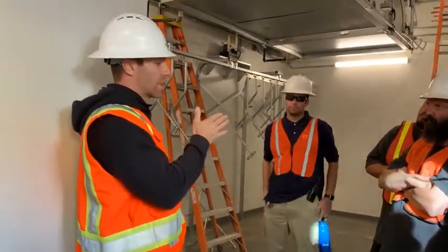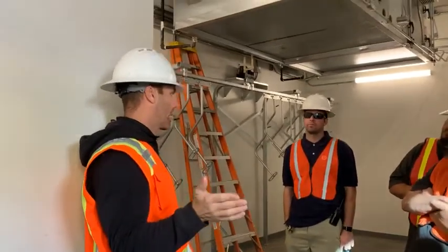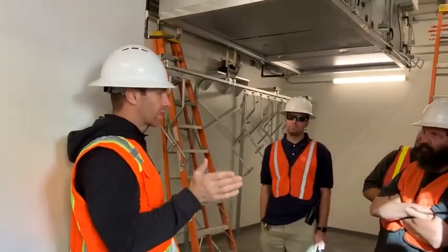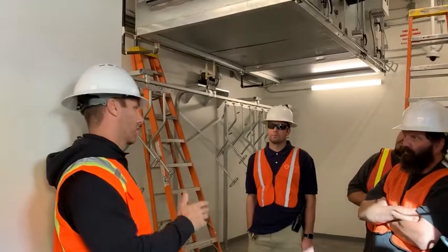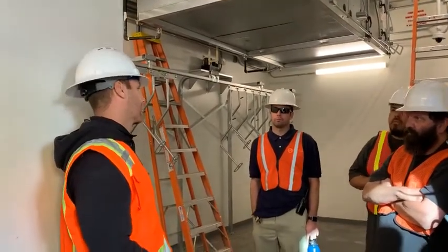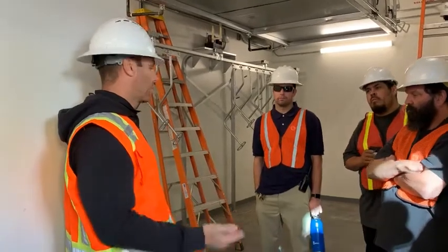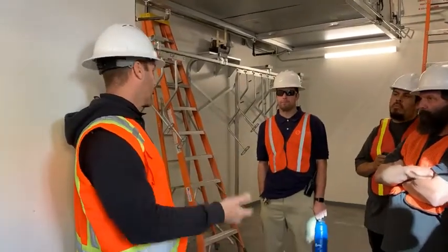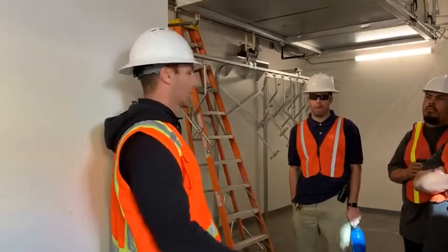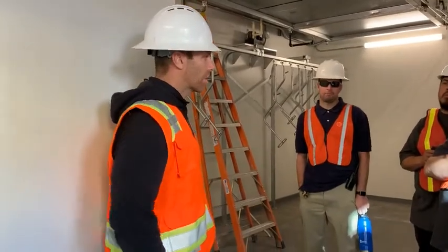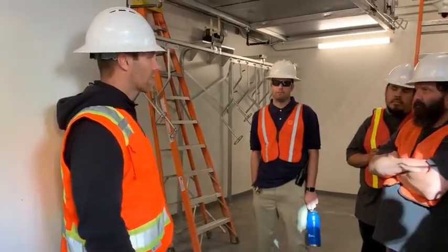It's going to be rare that your full LED board will go bad, and the life expectancy of the LED board, from my understanding, is longer than the driver itself. The LED board's not doing that much. The driver is what is capable of bringing 277 to 12 in the low voltage and dimming and all that. So that would be your typical scenario.